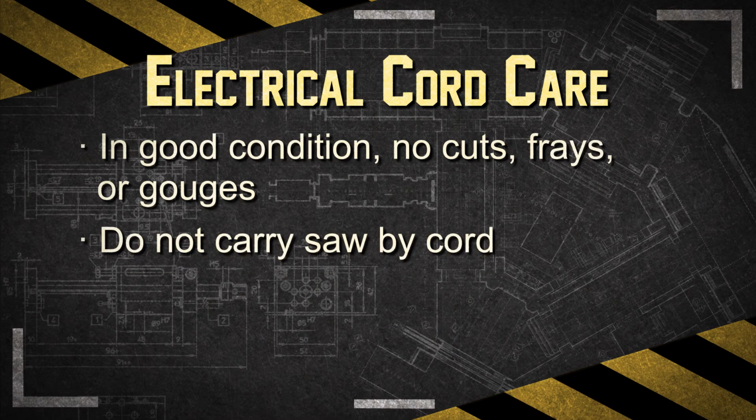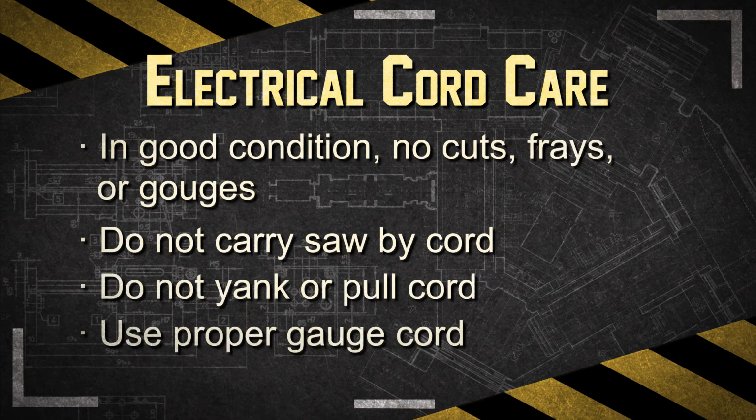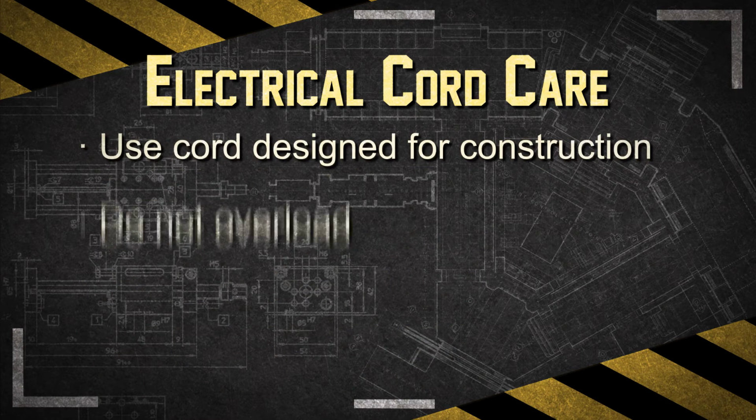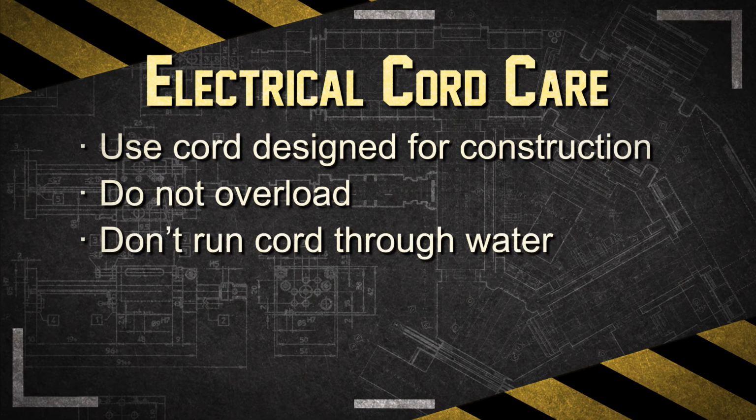Do not carry any saw by its cord or attempt to disconnect from its power source by yanking or pulling the cord. If using an extension cord, make certain it's the proper gauge and designed for construction usage so as not to overload or overheat the saw, and avoid running your electrical cord through any standing water.